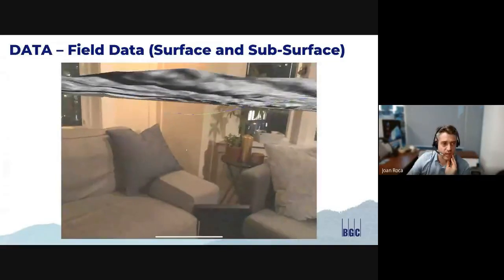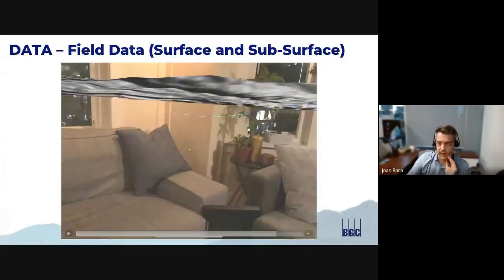If you look very closely down at the bottom of the image, in the center, and I will pause the video here if I can, there is this area where it should be straight, and you can see that there's been an uplift. You can see that the pipe has been pushed up, and that's because the toe of the landslide is just intersecting this location. It's just pushing the pipe up.